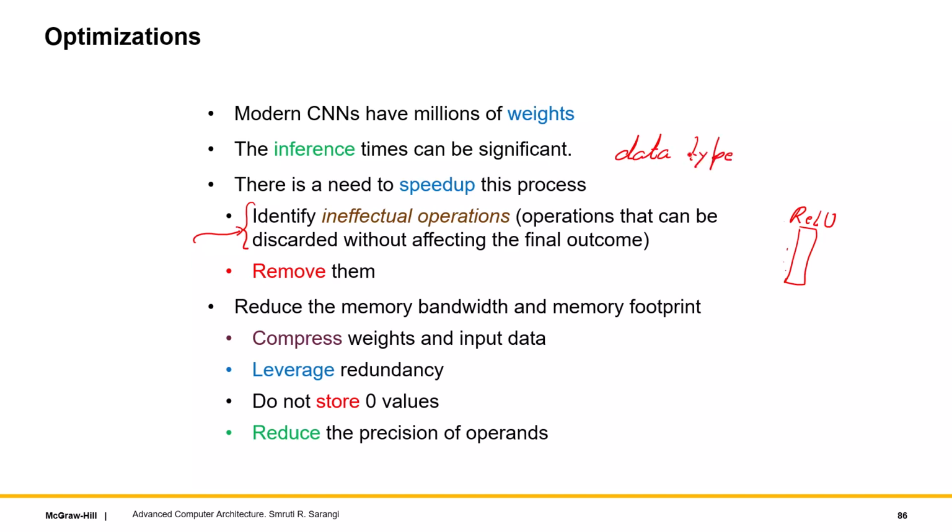Typically, you avoid using floating point or double precision, right? And even if you do use floating point, you try to tweak the number of mantissa and exponent bits such that you store data in as compact a representation as possible. In general, for neural networks, fixed point is preferred, something of the form 44.20 and so on, because you can store this as an integer and then do fixed point arithmetic on top of it, right? Fixed point in binary is typically what is preferred.